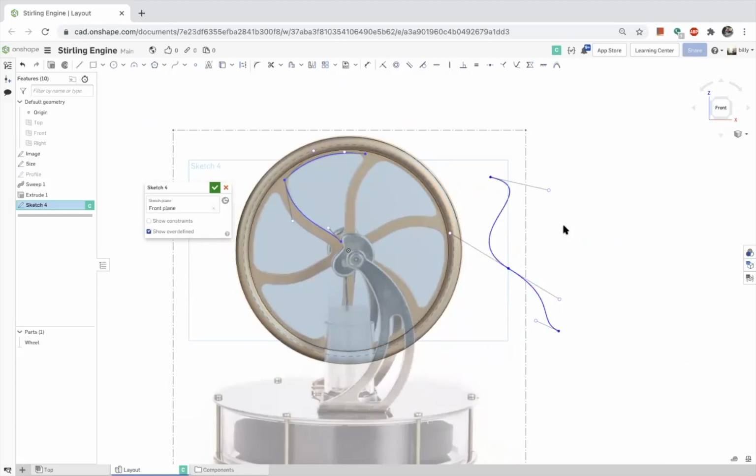And the way that I make that determination is here's an inflection, that's one. Here's an inflection, that's one. Here's an inflection, that's one. That's another one, another one, another one. You can very quickly say, I can represent this shape with one spline, but it's going to have multiple segments. It is very rare that I use 3-noded splines. 90% of the time that I'm using surfaces, I am using a 2-noded spline. Okay, that's the same practice I use too.